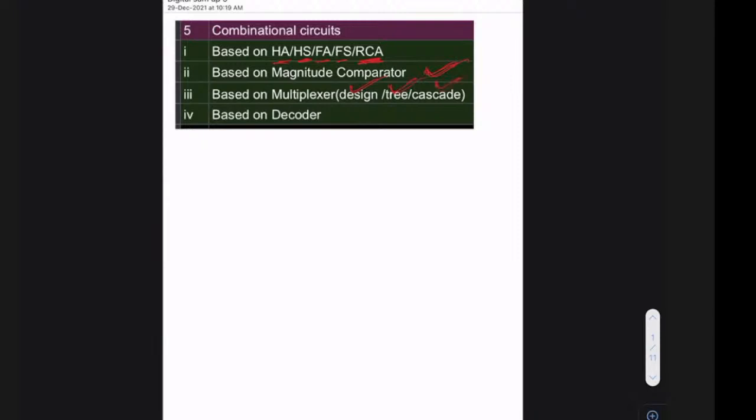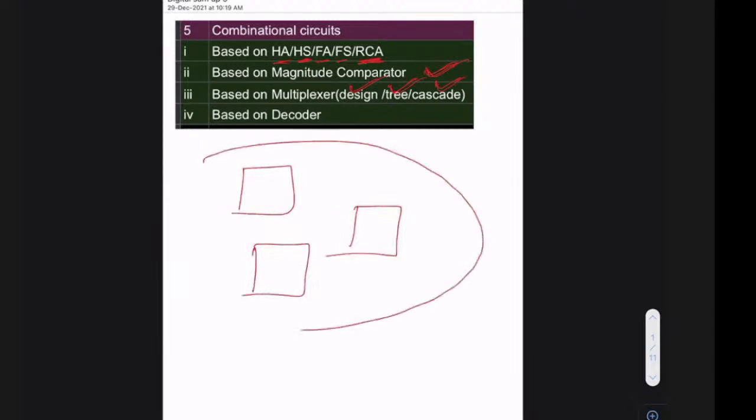Cascade structures are also a possibility, where 2 or more multiplexers are cascaded and they ask you to find the output expressions or the min terms or max terms of outputs. So that one question can be expected. And what is a multiplexer tree? This is what a multiplexer tree is. When we design bigger multiplexers using smaller structures, the overall circuit is called a multiplexer tree.